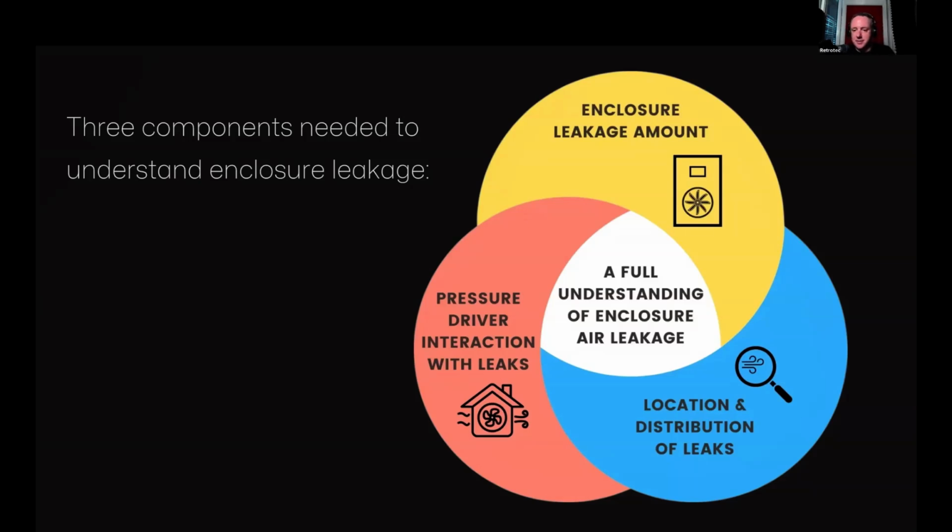But yeah, that next step is figuring out why that blower number is so high, if that's what it turns out to be. That's when we start using smoke machines, little handheld fog emitters, thermal imaging cameras, some probes with a high resolution manometer to look for pressure differentials around the house. That's how you really use additional tools with your blower door to hunt those things down.